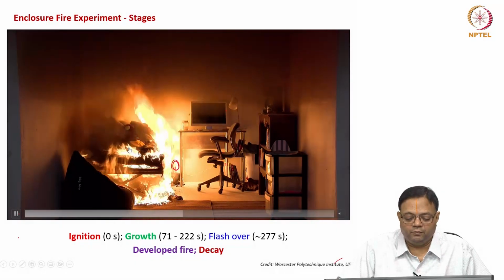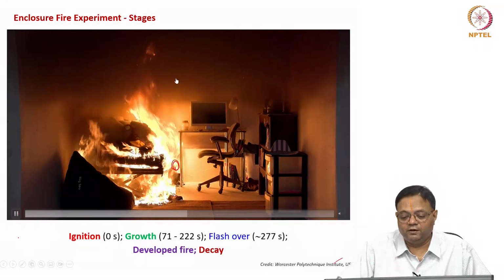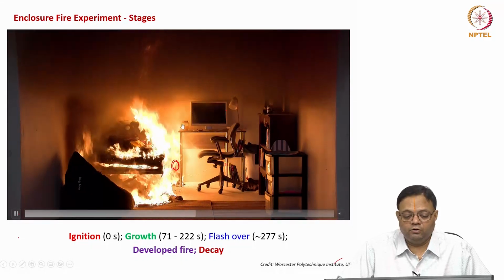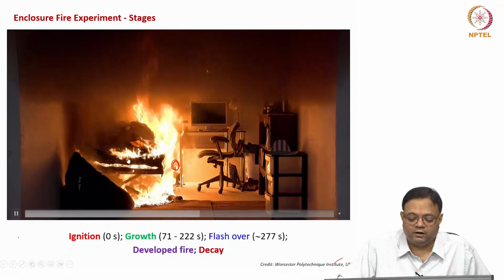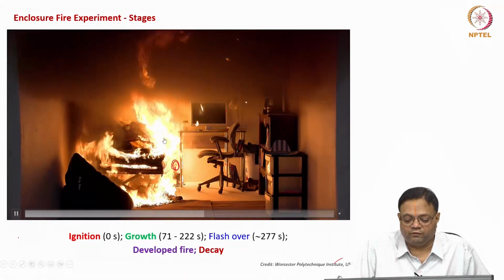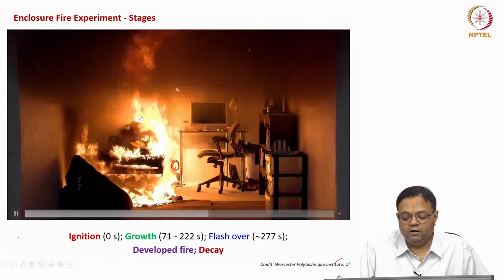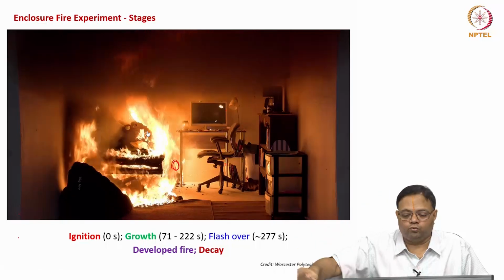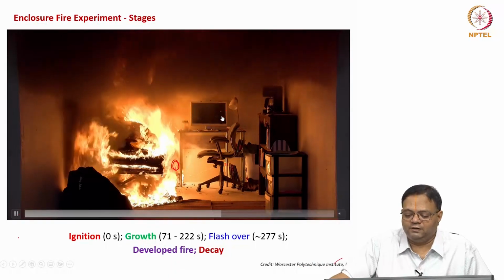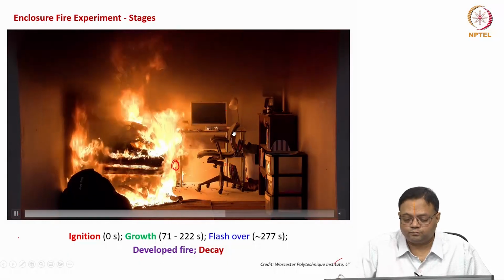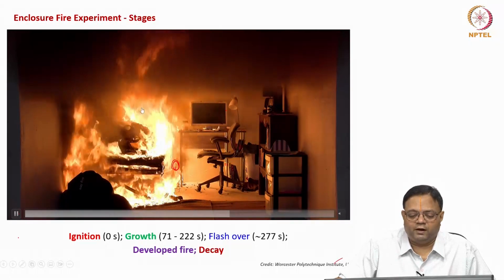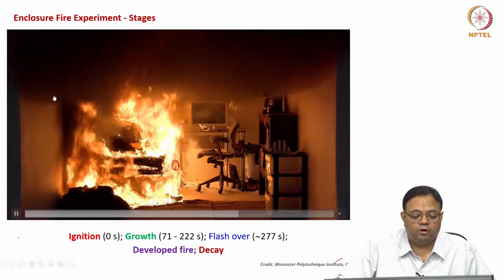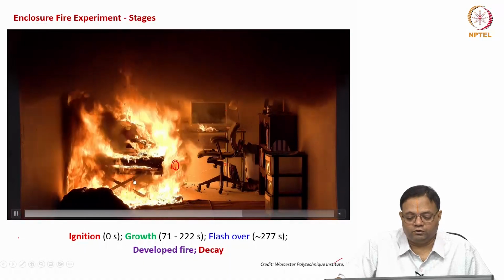Now you can see that this fabric burning throws up materials. You can see the particles being thrown up and falling on the other commodities. Okay, that is how the later part of the couch was ignited. When from the fire these particles are falling due to the fabric burning, because the loose particles are carried away, the burning particles are thrown to other commodities also. But this is not enough to ignite these commodities. You can see this. And now you can see the violent fire, the smoke generation near the walls, accumulation of the smoke, oscillation here you can see, the entire couch is vigorously burning.